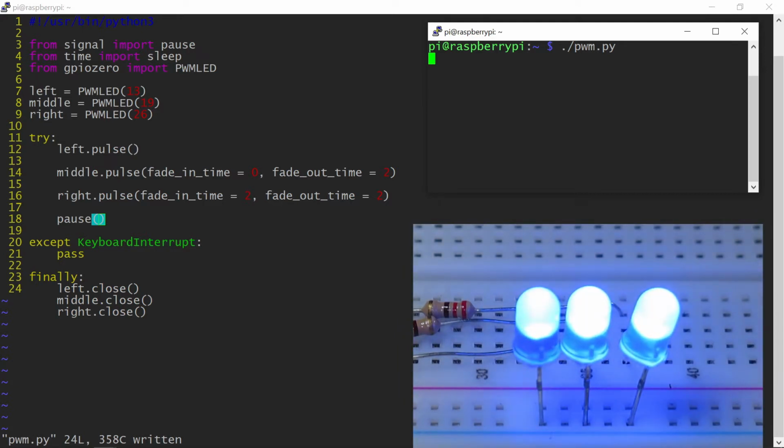Although this is software-based PWM, which makes it subject to some amount of jitter, this actually works quite well. Any flickering that you may see right now is just video recording artifacts, as the LEDs pulse at 100 Hz, while I record this at 24 frames per second, so this does not align perfectly. In real life, that actually looks pretty good.